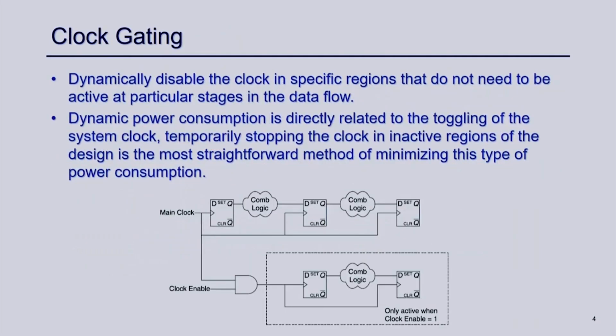Primarily, the techniques we are going to talk about related to power optimization, or making the design run on low power, target either reducing the capacitance or the frequency of your design. Capacitance means the number of togglings in your design. These are the two key parameters, and most of the optimization techniques applied in digital designs play on these two parameters only. So, let us move on.